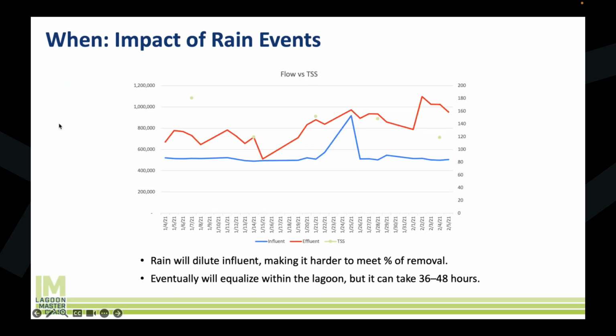I think that one of the big things with the time of day reading of samples is whenever you pull your samples, just keep it the same. Keep it the same time of day. Don't vary it, because it's hard to compare one sample that was pulled in March at 5 p.m. and one sample that was pulled in March at noon. It's hard to compare the two because they're going to vary based on algae growth. And so just pick a time of day, keep doing it at the same time.